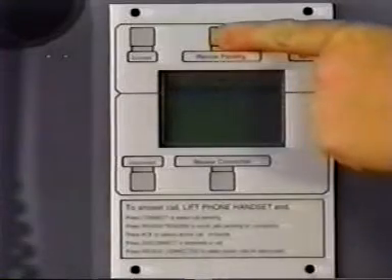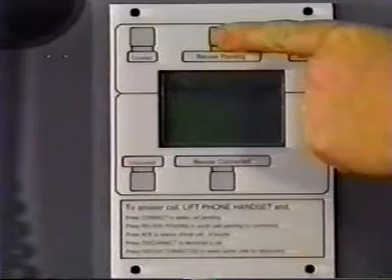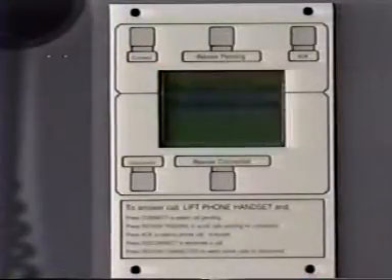If multiple calls are shown in the display, stop the call identifier sequencing by pressing the Review Pending switch once. Each additional activation of the Review Pending switch manually steps the display through the list of incoming calls. When the desired call appears on the pending calls identification line, stop stepping through the calls. To answer the selected call, press the Connect switch.